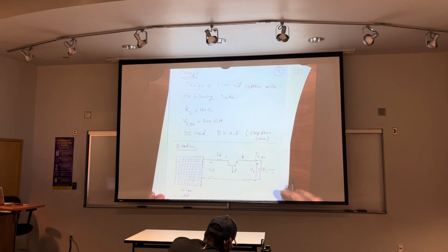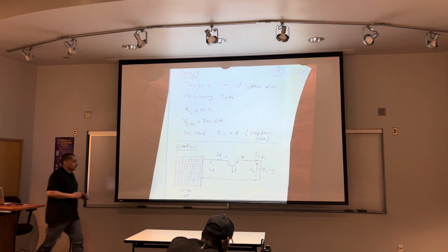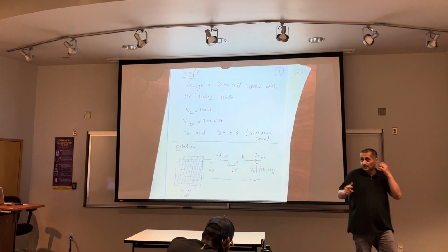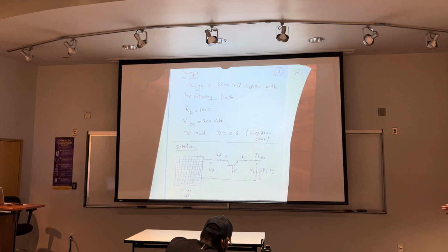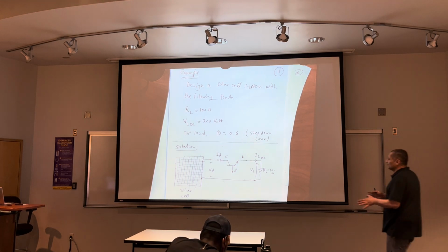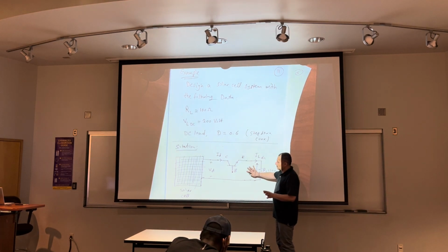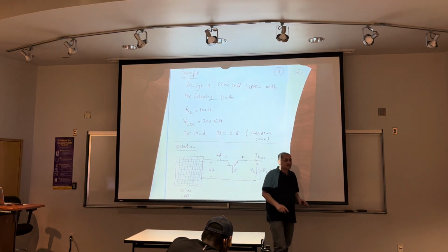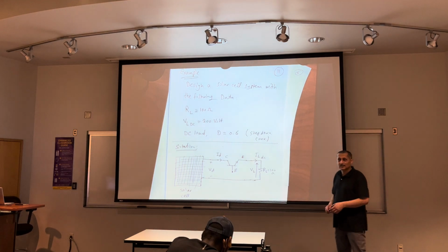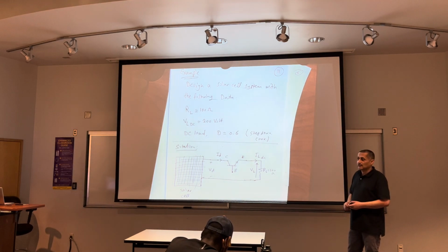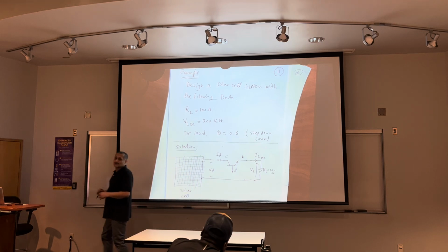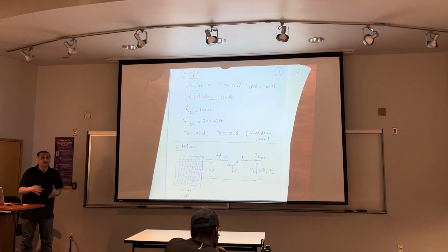First step, we draw the circuit diagram, okay? And then we will design. You are the designer now. First step, we draw the circuit, then we should calculate VD and ID. Okay, VD and ID. Then after that, we will design the solar cell panel or panels.